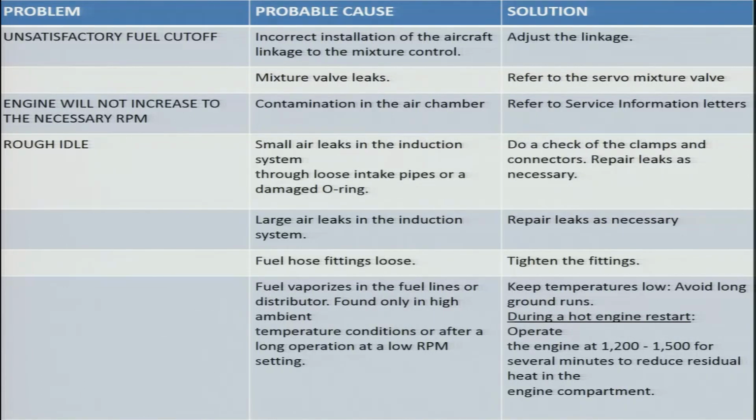There may be small air leaks in the induction system through loose intake pipes or a damaged O-ring. So, in the induction system the pipes might be loose or the O-rings might be damaged, and from there also there may be some air leak. In that case we need to check the clamps and the O-rings. If required, we need to replace them and fix the air leakage from the induction system. Apart from small air leaks, in some cases there might be large air leaks in the induction system, and then it needs to be repaired.